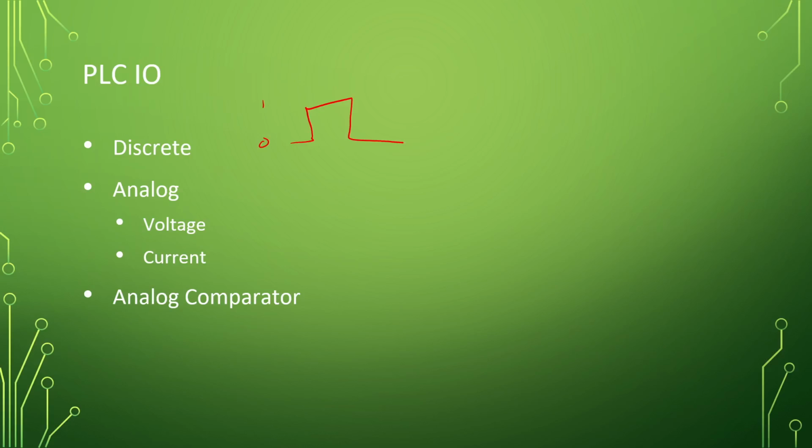Stepping back to the world of discrete for one moment, the other option nowadays with discrete is a VFD. VFD, variable frequency drive, is how we change the speed of induction motors: we change the frequency of the power going to them. Traditionally here in the US, we have 60 hertz frequency for our AC, and the speed is always based off that 60. But if you need to slow a motor down or speed it up, VFDs are what we use, and they are literally changing the frequency coming out. Normally you'd have your frequency, something like this. That'd be your 60 hertz, and if you had a slower one, say 30, it would be like this. We're just adjusting the frequency of that sine wave. That's how we control things.